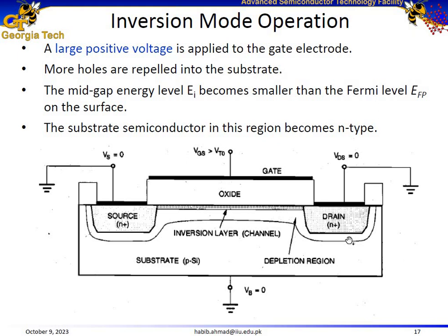Similarly, in the previous lecture we also discussed the operation of the p-n junction diode. Here we have an n-type region, and here the substrate is p-type. So at this edge we form a p-n junction, and in a p-n junction there is a diffusion of carriers across the metallurgical junction, resulting in a depletion region, which is void of electrons and holes.